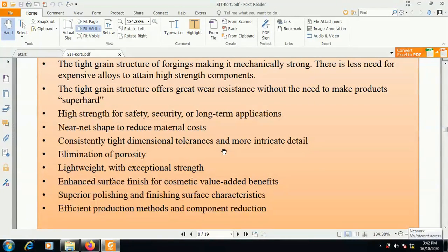Consider half die cavity attached to the punch, and half die cavity attached to the anvil. In that we are compressing the material, and the final product shape is die sunk, which means dies are manufactured by the die sinking operation. That's why near net shape is produced and very little scrap is generated in the forging operation.